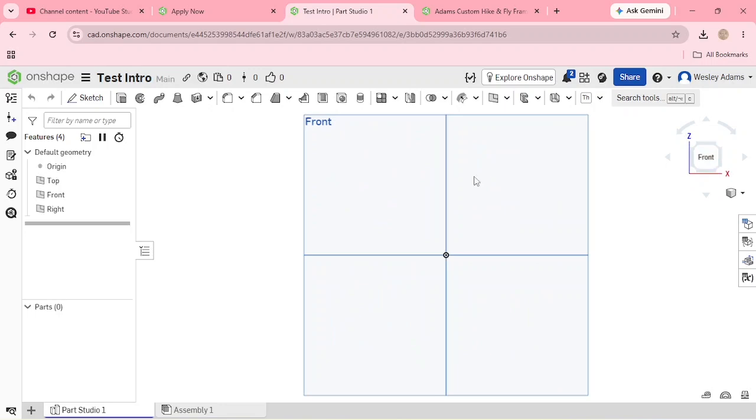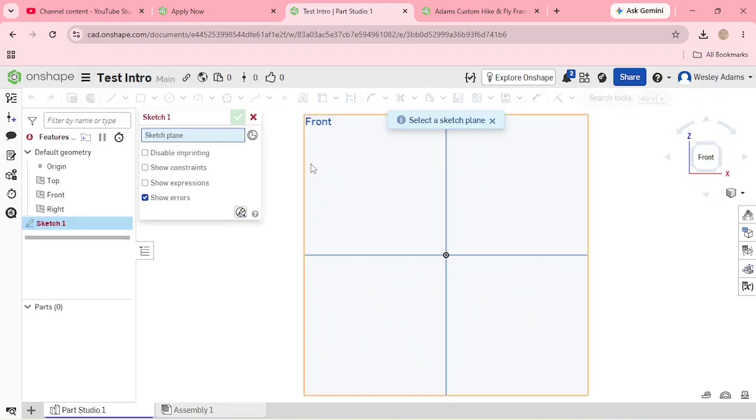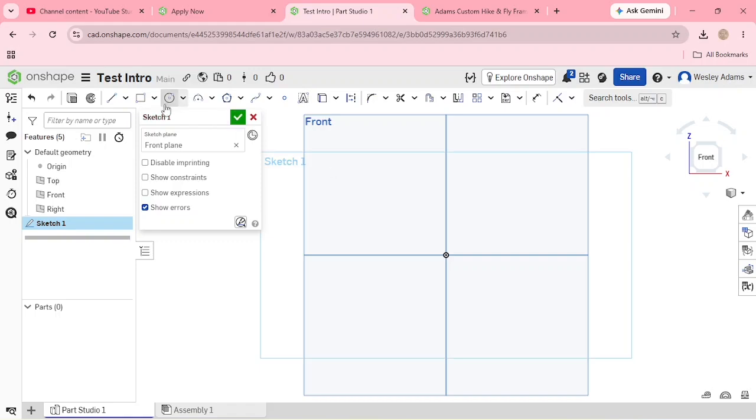So let's go front. Let's left click here on this sketch, left click front view, left click center point circle, come down here and hover over the center, drag that out. Don't worry about the size right now. Left click again, hover over the center again, and then left click and drag that out. Left click up here in the dimension tool, pull this away and enter 0.315. The green check mark turns that off. Left click here, drag this away, 1 inch.